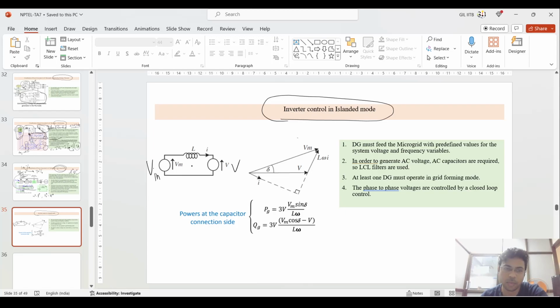The inverter is there and some inductive inductance is there. Like what I have shown you is that after the inverter output, if your inverter is giving a certain output, then you connect a certain L, C filter after that, and through the L you connect the common coupling to the grid.